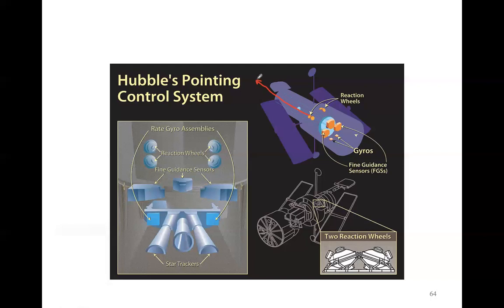As I said yesterday, when you point a star tracker in this direction, the precision you have for the orientation of the spacecraft along this axis is the least accurate. So what happens for a telescope is that your image is going to rotate along this boresight direction.